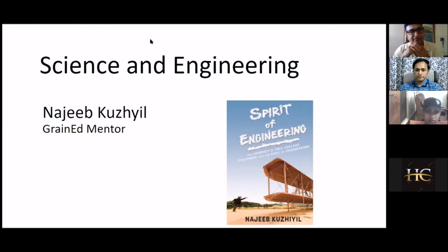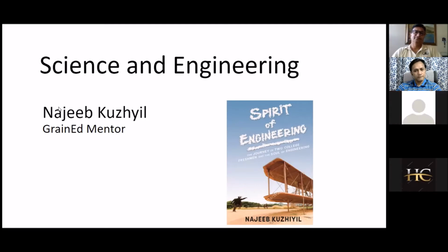Parameters to be considered: the terrain on which the bridge is built, the size and weight of the bridge, the amount of weight the bridge can carry, the height at which the bridge elevates, the material according to the lifespan of the bridge, like temporary or permanent bridge, the weather in the region where the bridge is built, the cost of construction, and weight distribution. Excellent work. Thank you, sir.